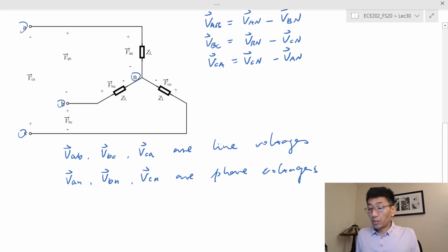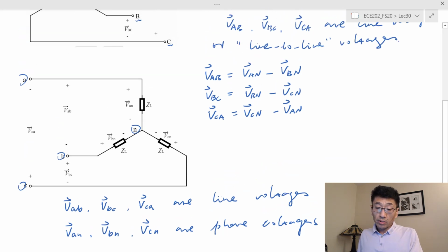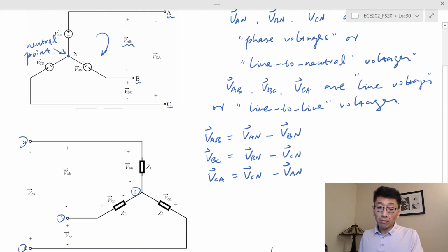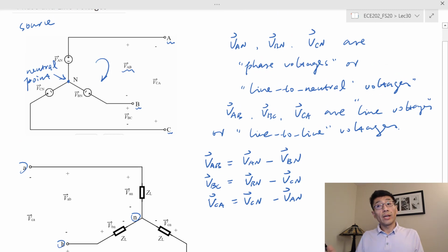Just to introduce this concept, this is very simple for a three-phase system. Typically, if you have certain electric machines, let's say a Tesla motor in electric cars, and they talk about the motor voltage, they're typically talking about the line-to-line voltage, the RMS value. And also for a transmission line, let's say the transmission line has a voltage of 230 kilovolts, that's the line-to-line voltage.